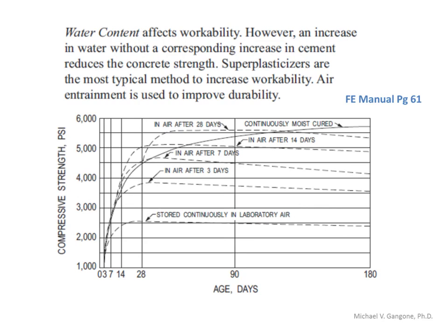Even after 28 days, we're still going to achieve a little bit more strength than what was at the 28-day mark, but it's not going to increase a whole lot, unless we have it in service for maybe a very long period of time. Maybe it will, but it will take a lot more time to gain any strength beyond a certain point.